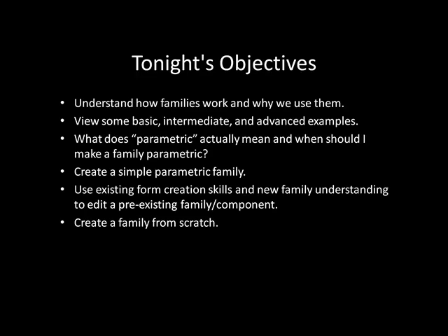And I guess an even harder question is, when should you make it parametric? It's actually good practice to always make them parametric, because you end up putting yourself in more of a bind if you don't put any parametric ties to the family, and then you go back and you want to edit it. You're kind of screwed. A family that's purely parametric can do whatever you want it to. It can change height, depth, width, thickness, materials, multiple materials. It might have math, calculus-based equations in it that make it do even more complex stuff.